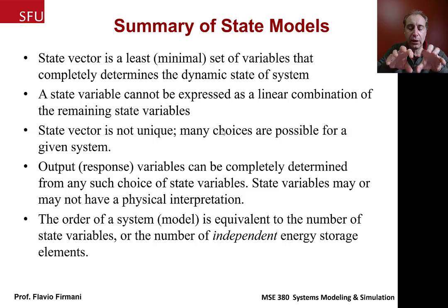Now, if these two gears are in mesh, it's not like we're going to have two energy storage elements. Perhaps we have one, and the other one is going to be a function of the first. It's the gear ratio that will determine the angular velocity and the torque that we're going to have on the other gear.